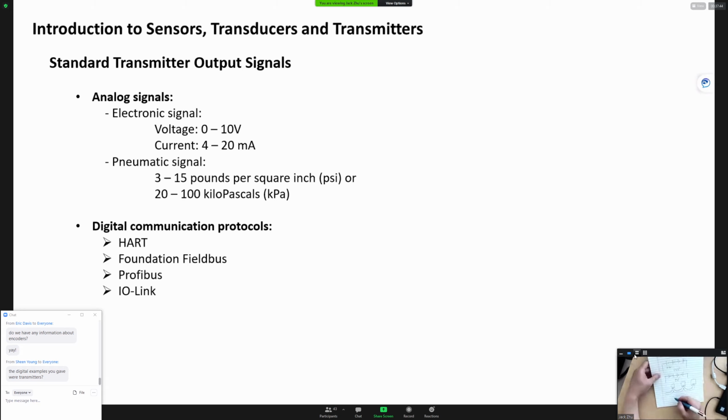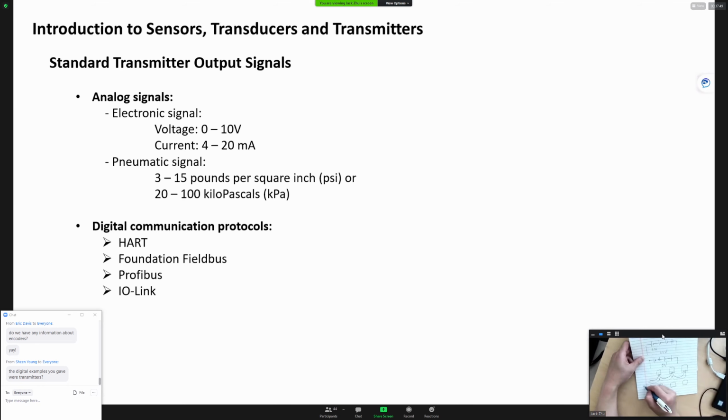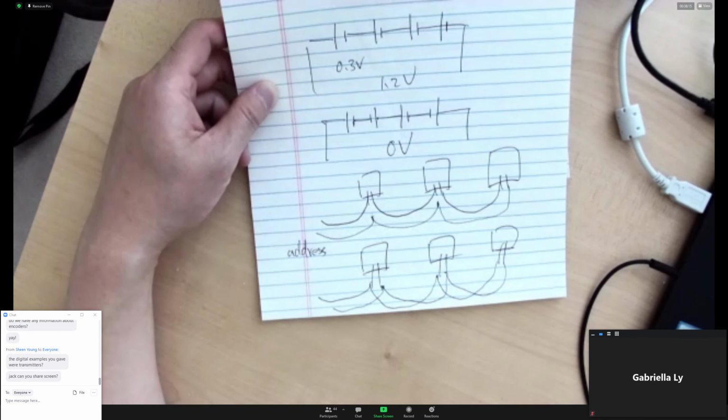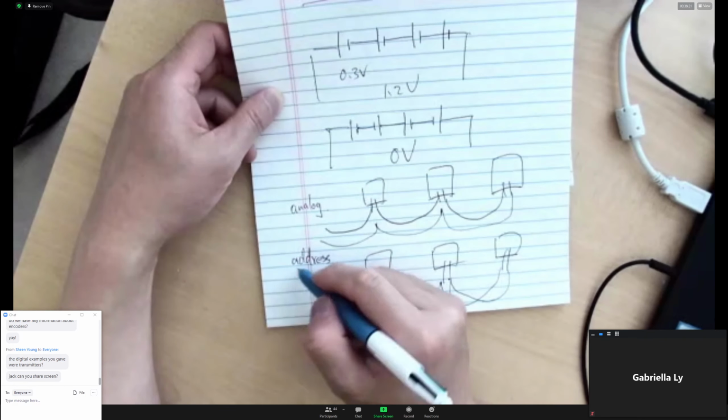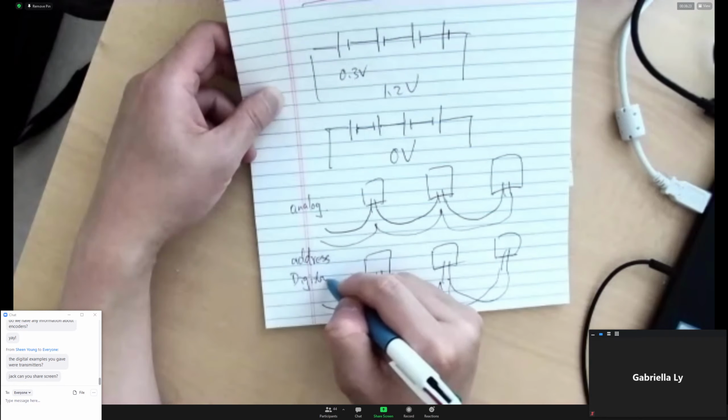But when you come to the new one, if you install a fire alarm system now, they call it the addressable system. They still have two wires, but you bring your wire in, wire down here, then you can keep going to the next one, keep going to the next one. So this is the old analog system, and this is the new digital addressable system now.